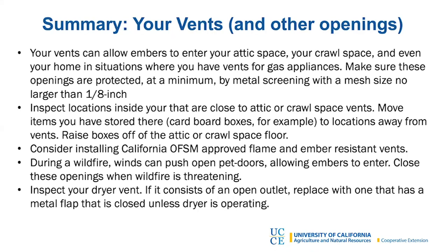There'll be lint that will accumulate in these dryer vent outlets and ducting, and they can be ignited by embers. So a louvered vent or a metal flap type vent that is closed all the time, except when the dryer is operating, is a better option.